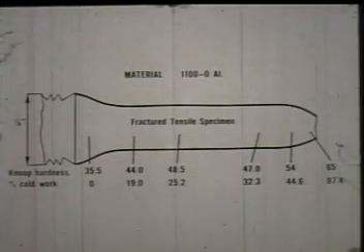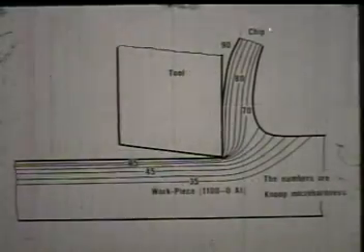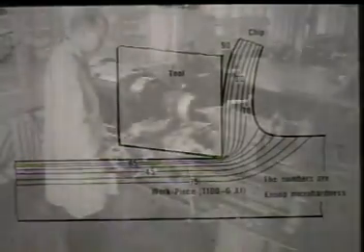By comparing the values of Knoop hardness in the tensile specimen to those of the machine surface and chip during low-speed machining, it is evident that there is a thin layer on a machine surface that is work hardened the maximum amount that the material can endure.